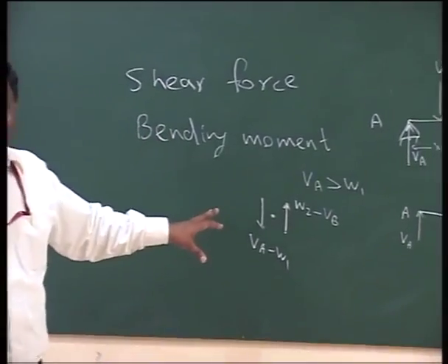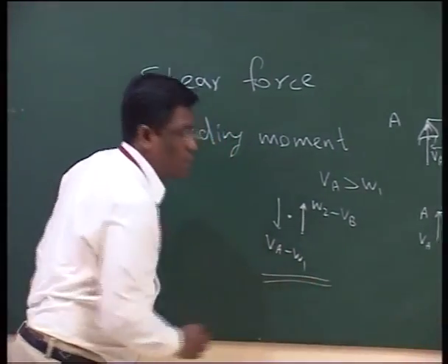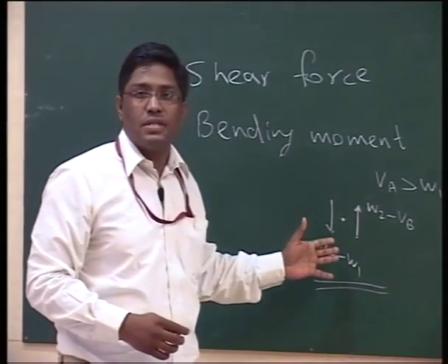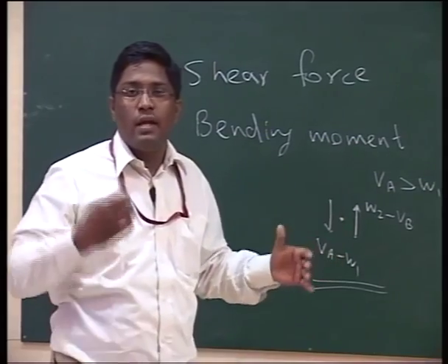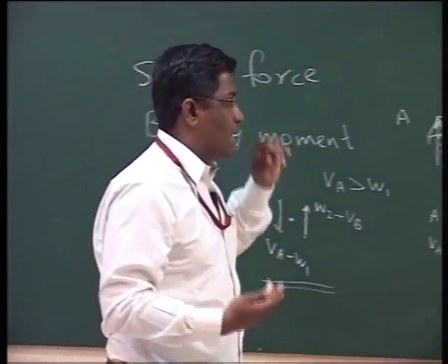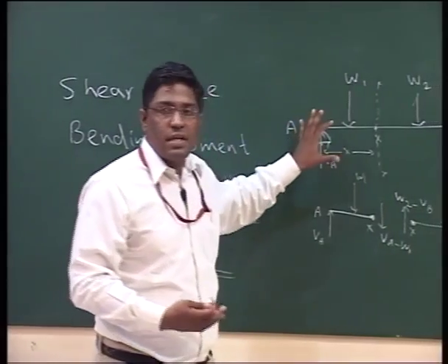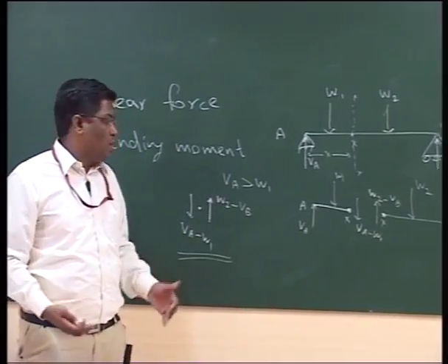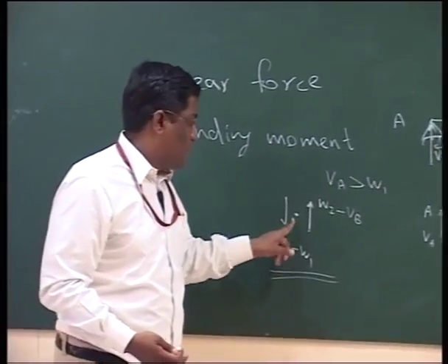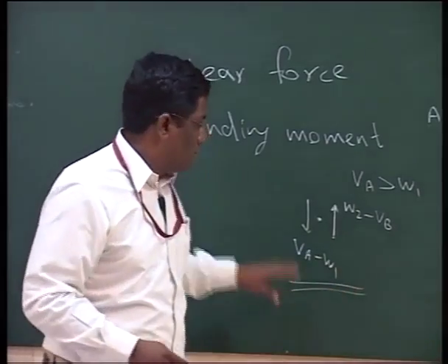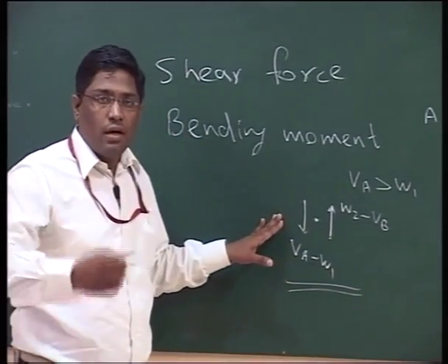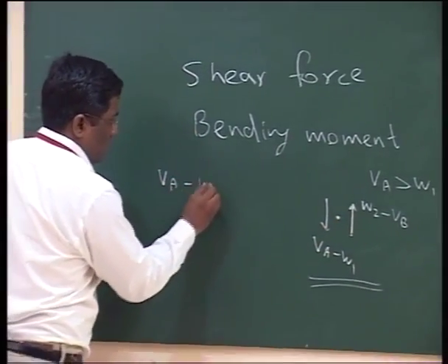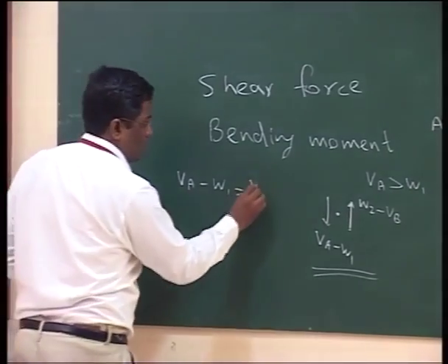So now we can see from this diagram that at every point of the beam there are always two forces applied, which make every point in equilibrium, because as I said earlier, if the beam is in equilibrium, then every part or every point has to be in equilibrium. So in this particular case, this point is subjected to two forces which, no doubt, we can quite easily see are in the opposite direction. Now let's see if they are equal, they have to be, first of all, to be in equilibrium.